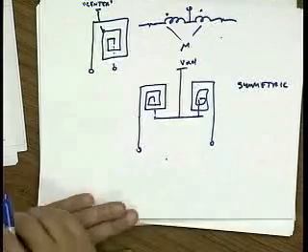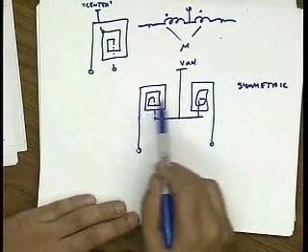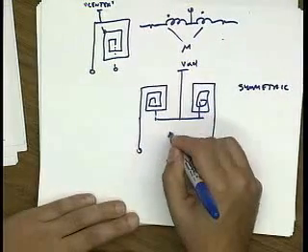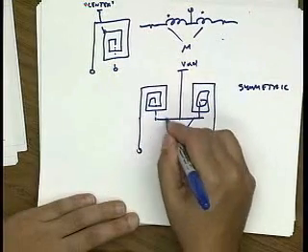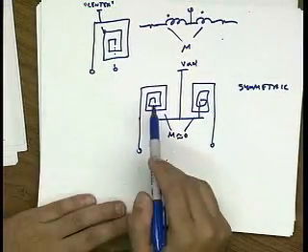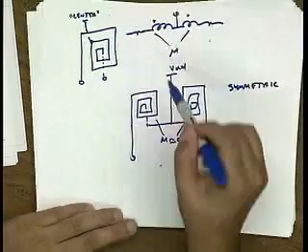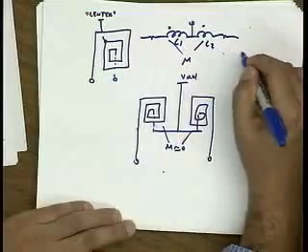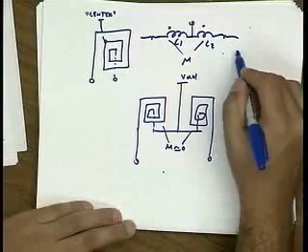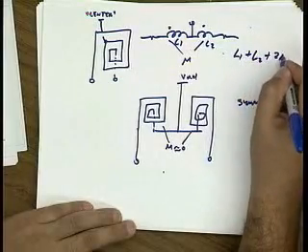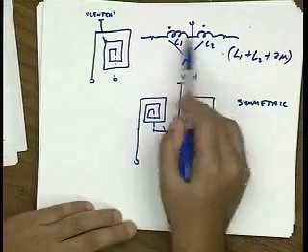But what you see here now, because these two coils are far apart, this M factor, the mutual inductance, is small. And so to get the same value of inductance here, if you think about what's the total inductance of this guy, if I put a current in here, the inductance is going to be L1 plus L2 plus 2 times M, because they're mutually coupled.